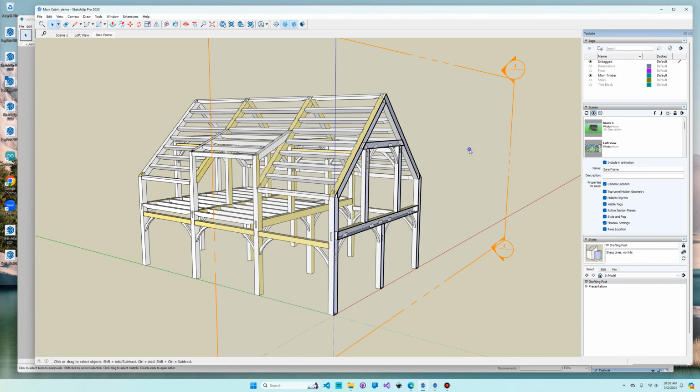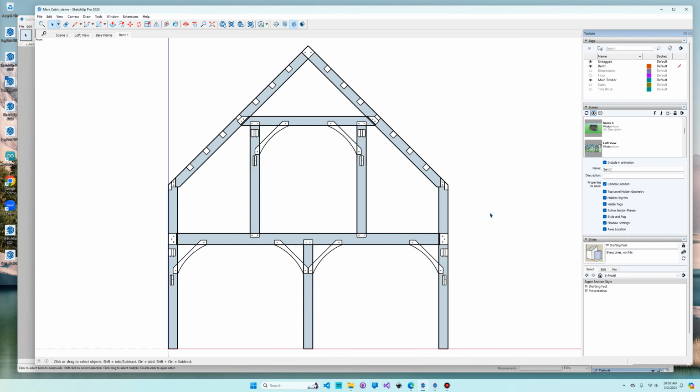And this time I'm just going to right click on the section plane and say Super Section. Now look what it did. It created the section cut. It aligned the view. It took us into the 2D camera, and it centered the model right on the screen, just like all those manual steps that we did before we used the plugin.